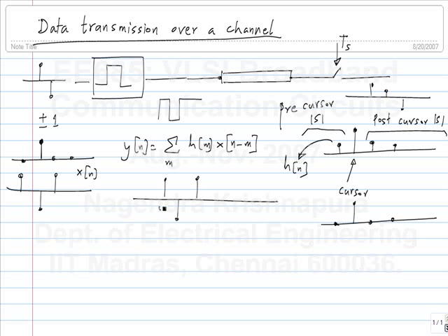Let's say this is the input sequence 0, 1, 2, 3, and we are interested in the output at symbol 1. We assume the response looks something like this, and then we have to flip this. So all of the post-cursor ISI comes to this side. The main part of symbol 1 gets multiplied by this, and the previous symbol gets multiplied by this, and that also affects symbol 1. The one before that gets multiplied by this and also affects symbol 1, and so on. All of these affect the symbols that are following. And if you had something here, then this is symbol 2 affecting symbol 1. So that is the precursor. It's just the impulse response, that's all.